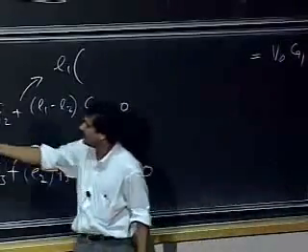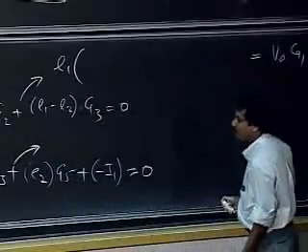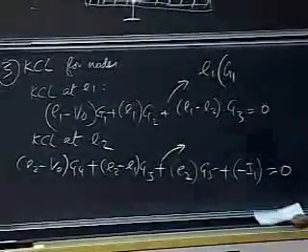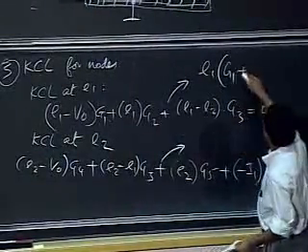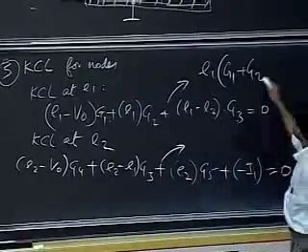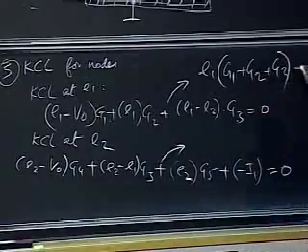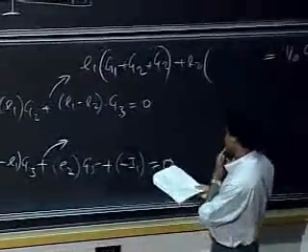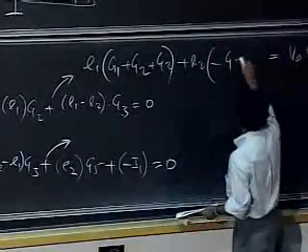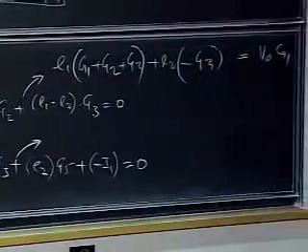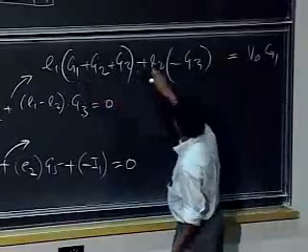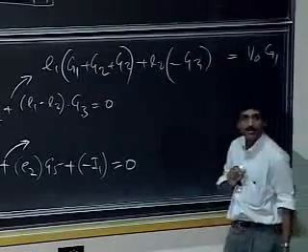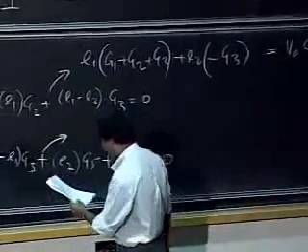And let me collect all the values that multiply E1. So I get G1 as one example, I have G2, and I have G3. And then for E2, I have minus G3. Okay? So I've simply expressed this as the element voltages multiplied by some terms in parentheses, and I put my external sources on the right-hand side.